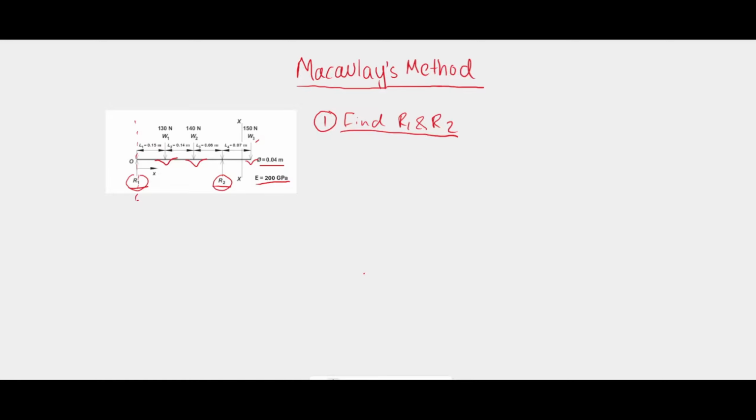So now we'll start by finding the moment forces that act when R1 is the pivot. As you can remember, the formula for moments or torque is equal to the force times the perpendicular distance between the force and the pivot. It is also important to set a direction for these forces. So let's say the forces acting upwards are negative and the forces acting downwards are positive. According to the principle of moments, the forces acting downwards or clockwise should be balanced by the forces acting upwards or anticlockwise.